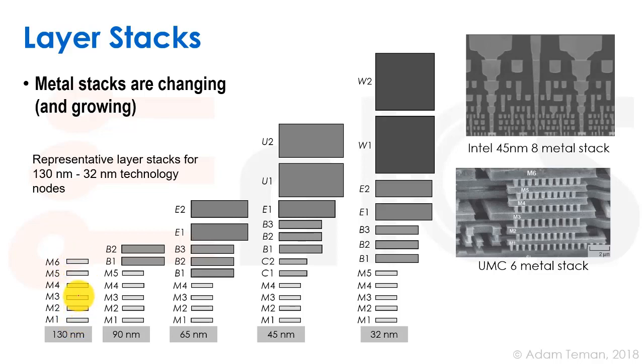The height of the metal layers are the same, and the distance between them and so forth. And therefore the DRC rules, the minimum spacing, minimum width, was the same. But as we continued to progress, we wanted higher metal layers to be thicker to reduce the RC and provide better power routing and maybe clock routing. And then as we progress, we have what we call X, Y, and Z layers.